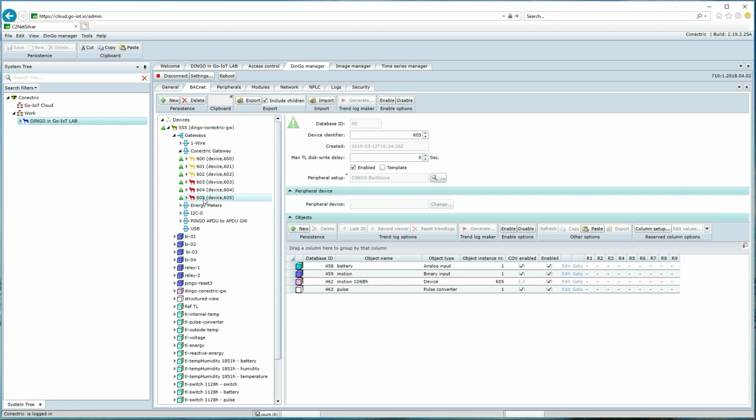You can now, if you want, either fine-tune the generic devices or have them as is. You can also, before you turn the sensors on, modify the templates or make different templates to get the exact BACnet functionality you want. So that's up to you. But we provide default templates that you can use right away also. So this explains how we auto-configure from sensor to BACnet.